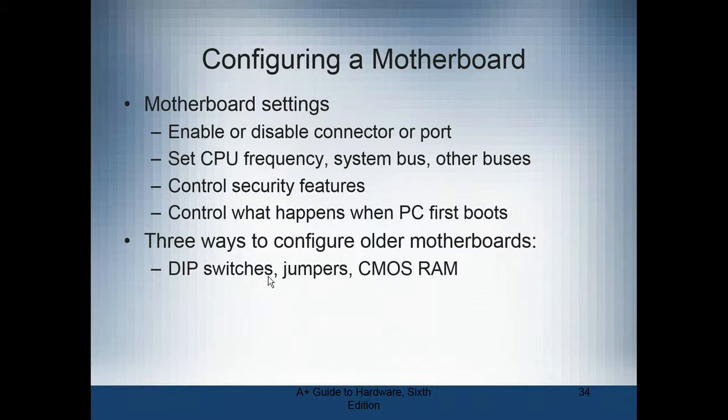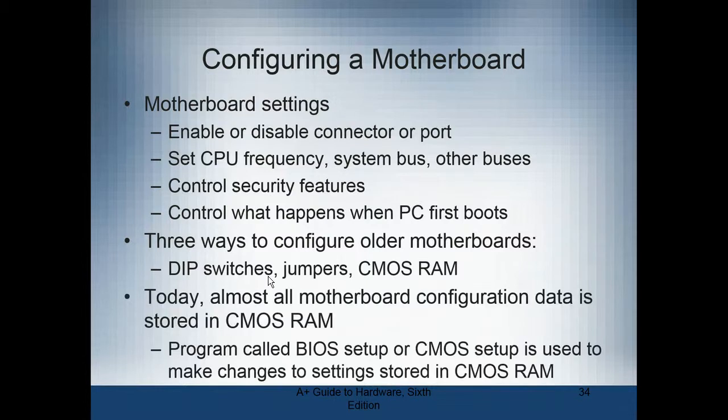You have to be careful about that when you're working on them. Be sure that it's turned off. Actually, when you're working on them, unplug it and wait. Usually you're going to have an LED that is lit when there is power on the bus. Wait till that power totally discharges before you start working on it. It'll probably be discharged by the time you get the case cover off, but be sure it is discharged before you start working on these things.